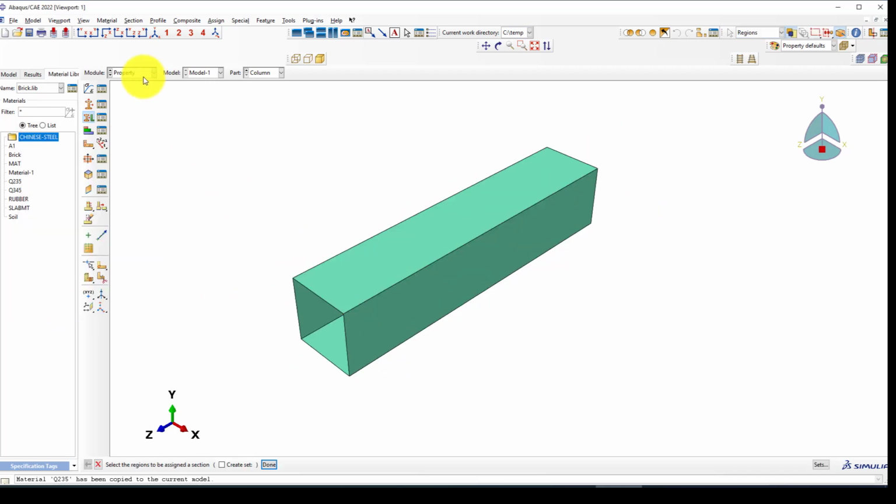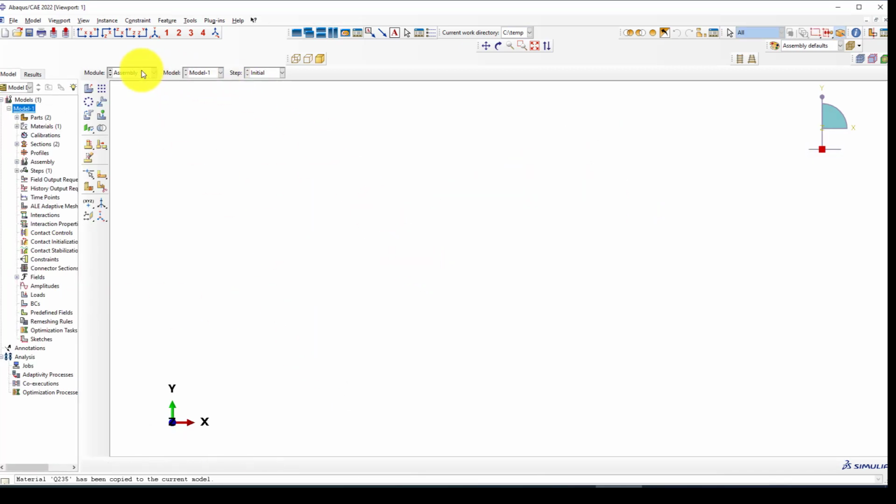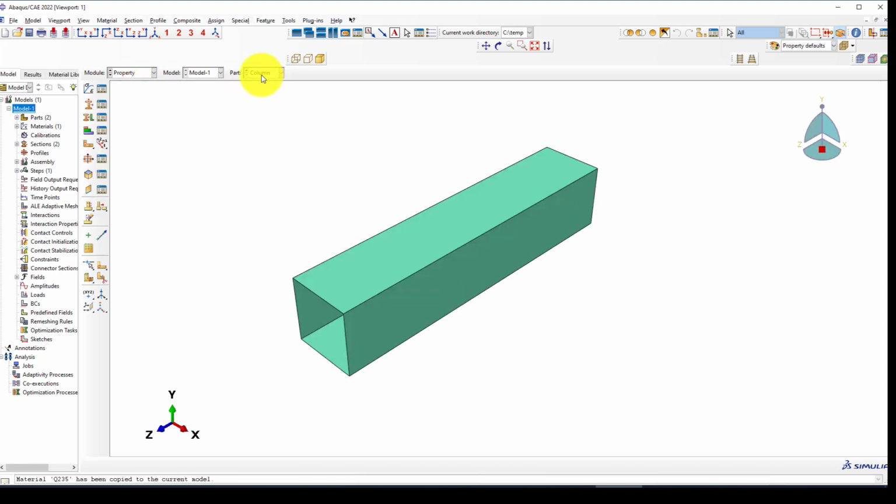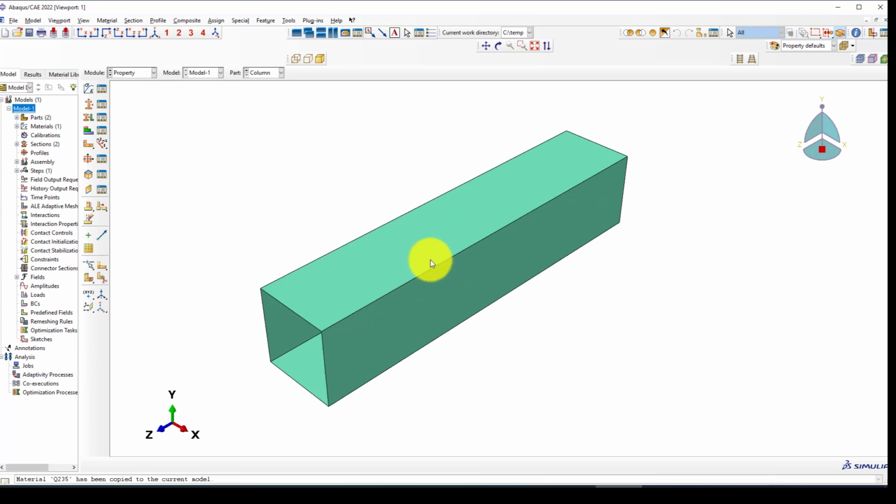Now it's okay. We created both materials, and before going to the assembly, I want to create some partition for the column because during the meshing and the contact, there will be some little distortion in that joint. So I want to prevent that distortion and also some non-convergence. So it's better to create some partition and create that specific line which is passing in the other elements.